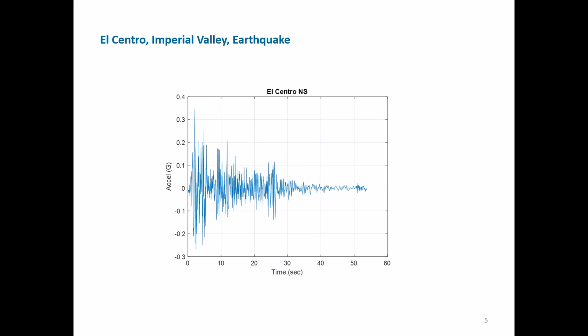But it's different in the sense that in earthquakes, the energy is down at much lower frequencies, mostly below 10 hertz, and in pyrotechnic shock, most of the energy may be well above 1,000 hertz. But we do have numbers. In fact, the peak acceleration is 0.35 Gs. Now, 0.35 Gs might not seem that it has much damage potential, but there's definitely more to that story because we need to account for the duration as well as the frequency content that goes along with it.